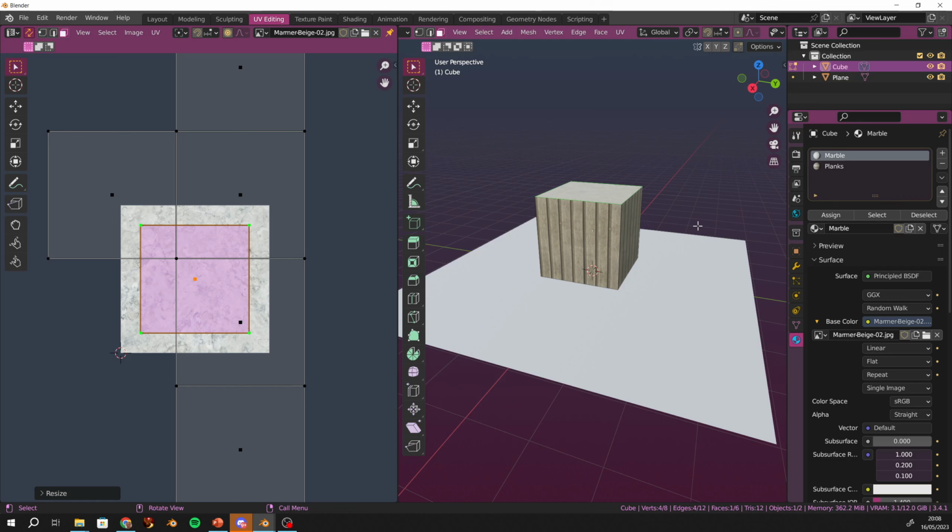The new way will be, in the future, that you upload your mesh with the material. Currently, the alpha viewer works so that you upload just your material. You have an option to click upload material, and then it will upload all the textures needed in one go. How nice, very efficient. But the textures themselves change. You still have a color map, and one normal map, so that's still the same. But then you also get what they call an ORM texture, which is ambient occlusion, roughness, and metal in one.